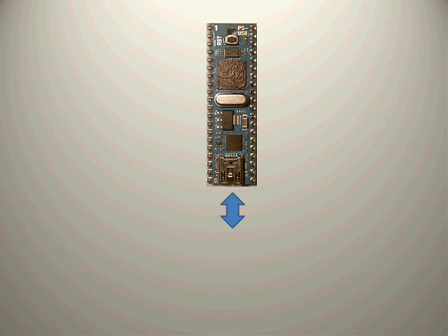The main interface of the Propeller chip is a USB interface to a personal computer, mainly used for firmware and application software download into the Propeller. It's a bidirectional interface, because in our case the pulse generator application itself makes use of the USB connection through a Windows client where all parameters are displayed and parameters can be adjusted.